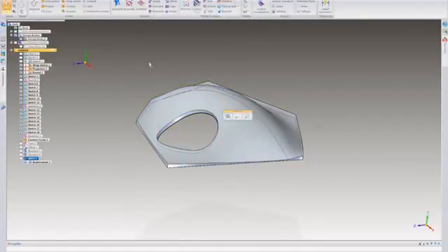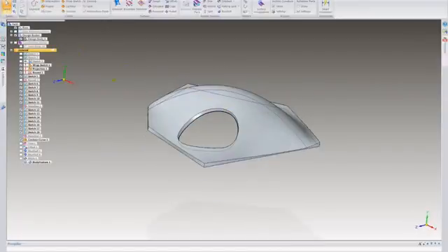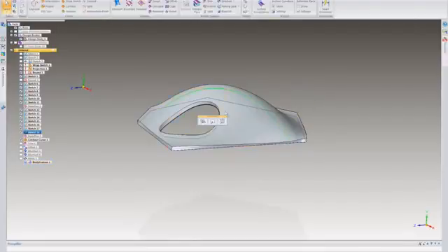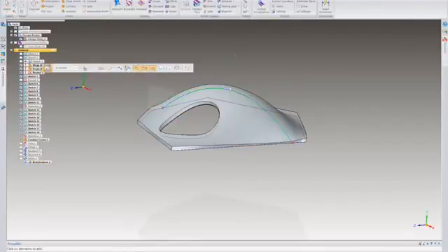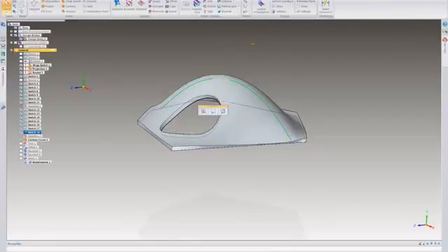And of course, it's going to change from that surface color into the solid color that I have. That doesn't mean that the sketch geometry and things like that aren't still viable. If I come back and find the sketch that controls the indentation on the top here, I can still take that. It's a little slower because it's doing a lot more calculations now that I'm doing a dynamic edit. So it may not be as smooth a transition as with surfaces, but it will still dynamically change and move to show you exactly what's going to end up before you commit and change it. There we go.